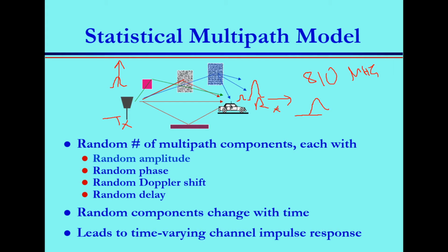And you have another. So if the receiver can resolve them, separate them, good. If all of them are reaching simultaneously at the same time, they will come on top of each other, and they will cause fading, fluctuation in your signal, because they may add constructively or destructively, and accordingly you always get fluctuation in your signal.